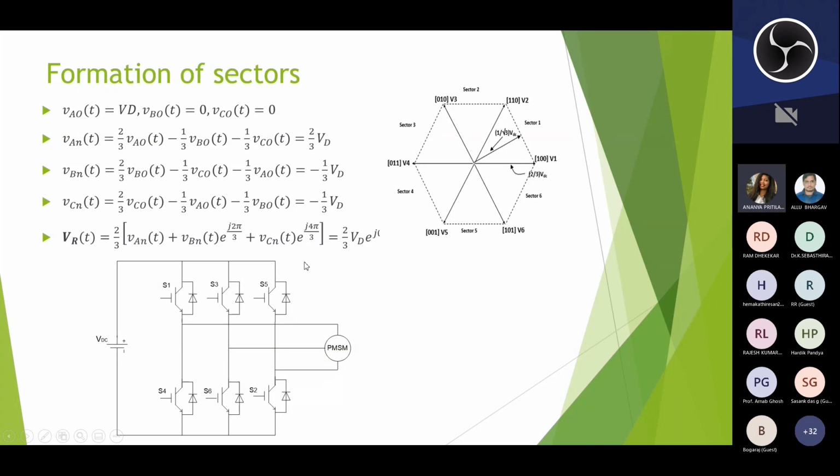For each PWM cycle, space vector PWM creates the proper gate drive waveform. This inverter is viewed as a single device that can transition between different states according to the number of switching states. For each state, SVPWM gives a distinct switching time computation. This technique works with almost all types of multi-level inverters and can be easily adjusted to greater levels.